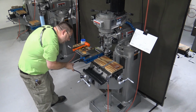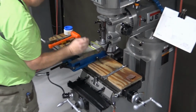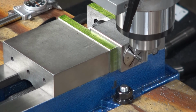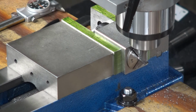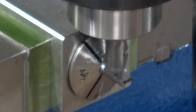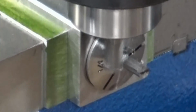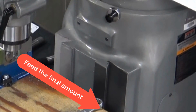I'm going to feed up 14 and a half. Start my machine. Repeat that process. As soon as I start to cut, my zero should be there, right? There's 200 thousandths. 400. 600. Remember we said that that arc was going to be there, so all I'm going to do is feed front to back, okay? And because the total destination is 620, now I'm going to feed back that extra 20 thousandths on the appropriate side so that I'm conventional milling, and then I'm going to mill across.